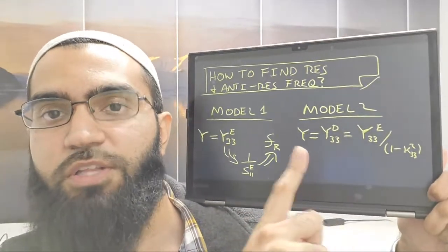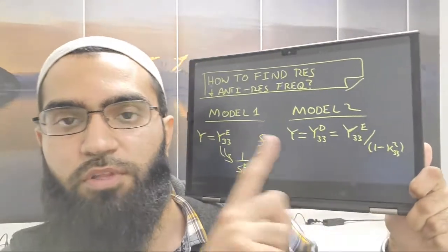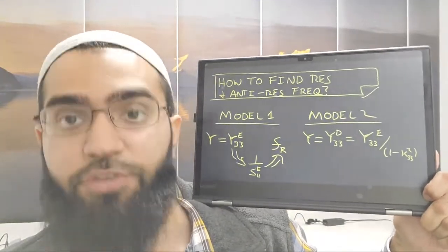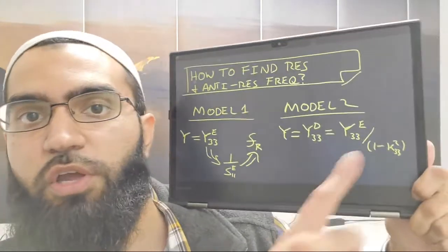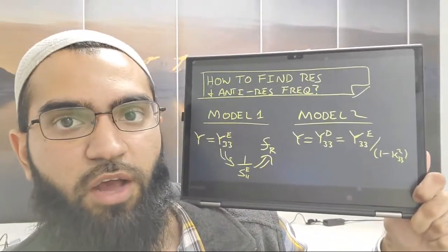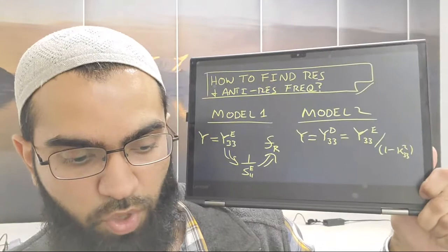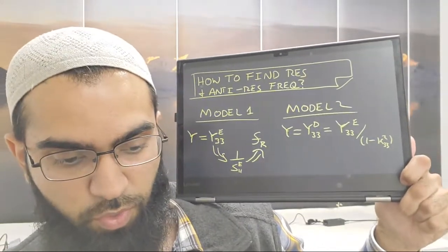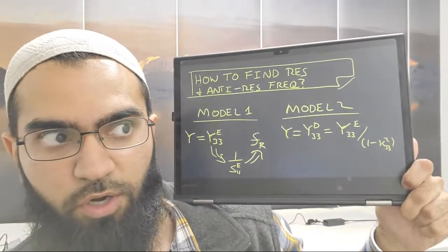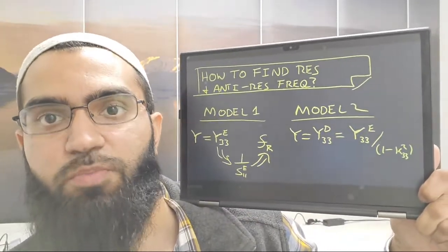Okay, so the second part is, let's say you model it isotropically, or even anisotropically. If you come up with the equivalent matrix for a constant electric displacement, which is the open circuit condition. You come up with the whole matrix, or if you're doing isotropic assumptions just for understanding and analysis, you would obviously have to make those properties according to what mode of operation you're using. If you're using an S11 or a 1-1 mode, or 3-1, you're not going to be substituting the wrong property in there. You're going to be looking at the property which is going to dominate your device most.